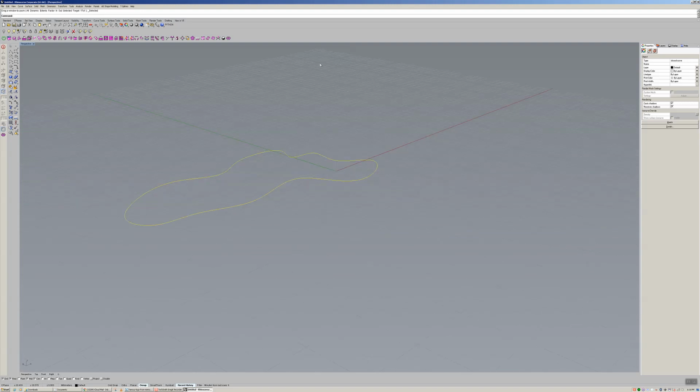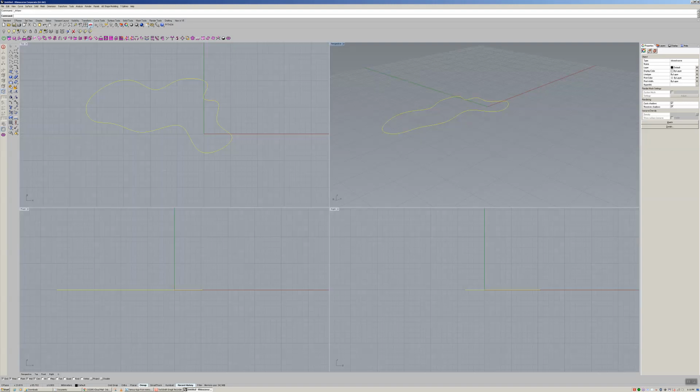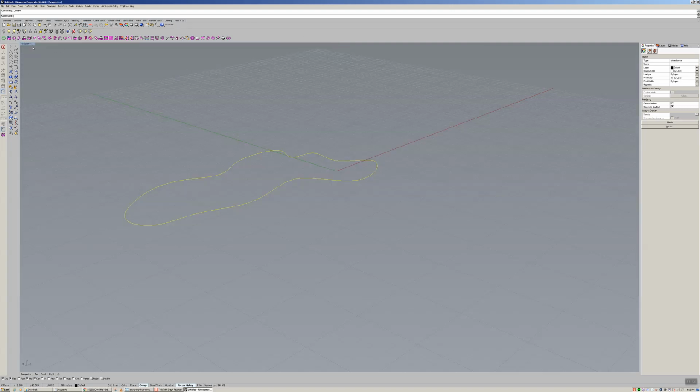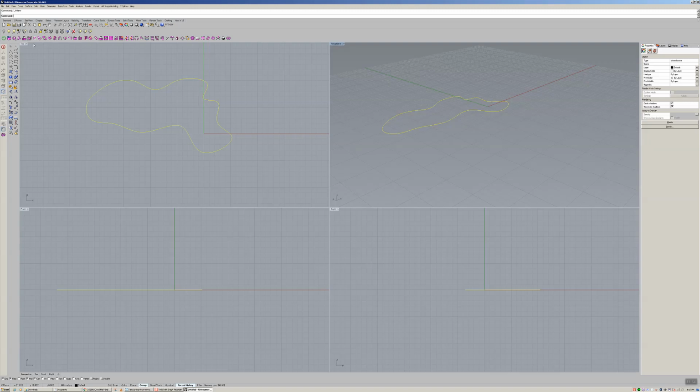And that's very useful, especially when you start to do other curves. So I'm going to draw a few more curves here. Now I went to clicking the 4-point view over here, which is the 4 viewpoint perspective right here. This icon's 4 little boxes, but you can just, again, click on the name. So if I'm in perspective, I go back and I click on perspective, I'm back into the 4-point view. Okay, so let me draw a couple more curves here.